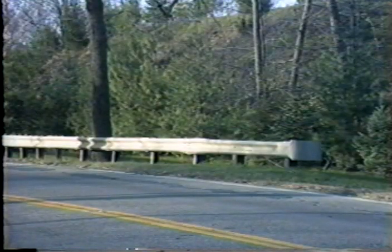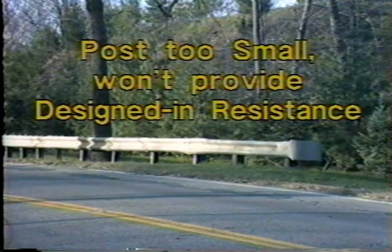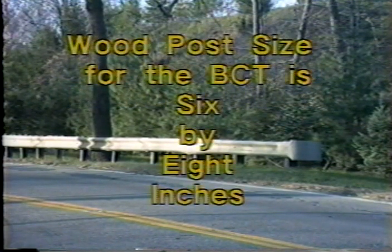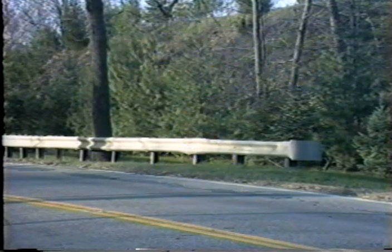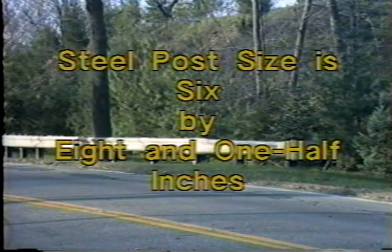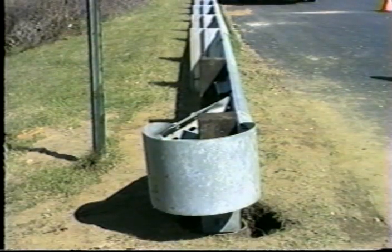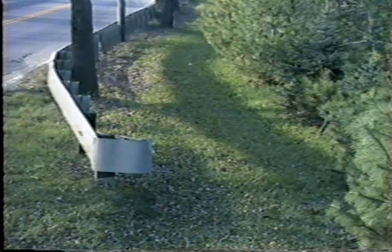Post size and spacing are obviously very important. If posts are too small, they won't provide the designed-in resistance when hit. If they're too large, they'll resist too much. Approved wood post size for the BCT is 6 by 8 inches. Normally, a Douglas fir post is used. Steel post measurements are 6 by 8.5 inches. Posts are set on 6-foot 3-inch centers. The first 2 are not blocked out to prevent fouling on impact. Although no more than the first 37.5 feet of rail functions as part of the system, the flare must be maintained beyond this point if so designed.